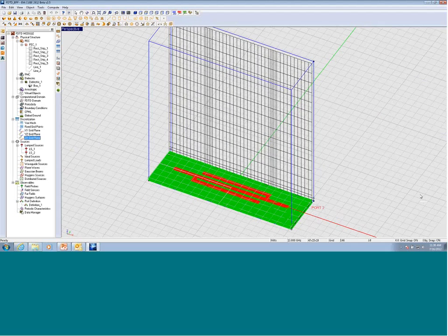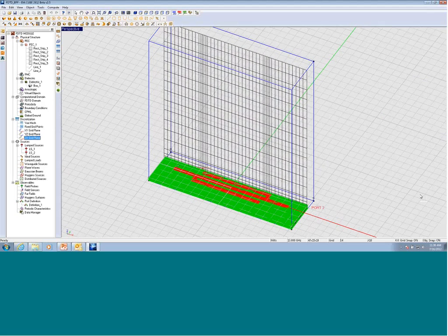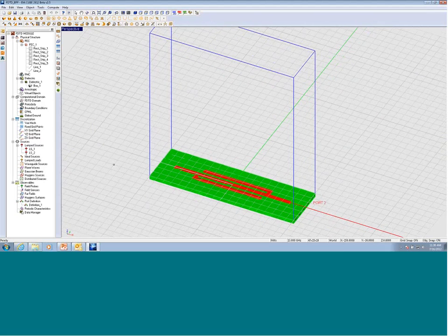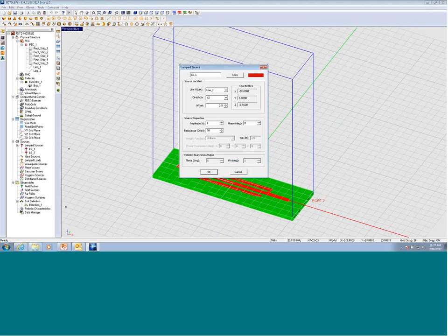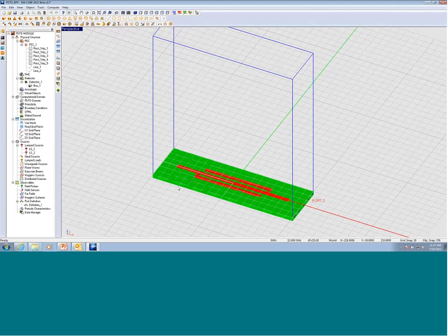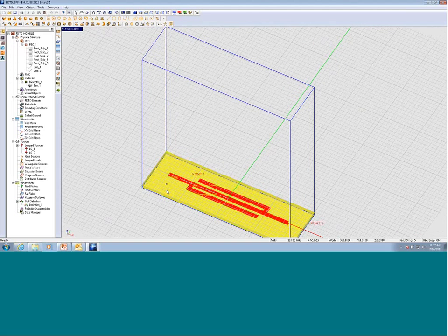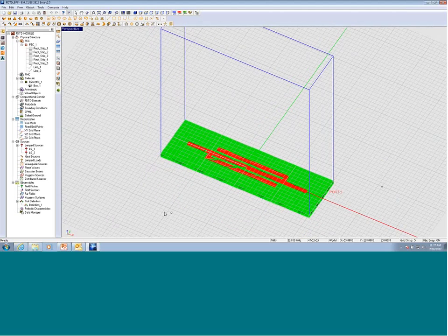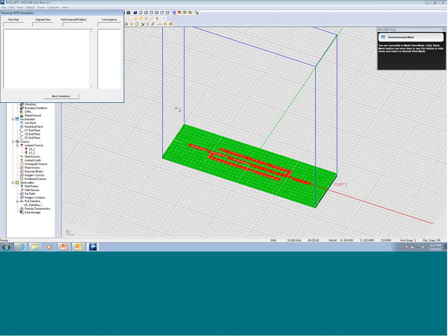This is when we define lumped elements or lumped sources. One lumped source is put here at the end of, or at the back of, line 1, or the first line, and the other one is put here. So these are the sources, and we define 2 ports, and now we can run the FDTD simulation. The setting says modulated Gaussian, and so we run this.